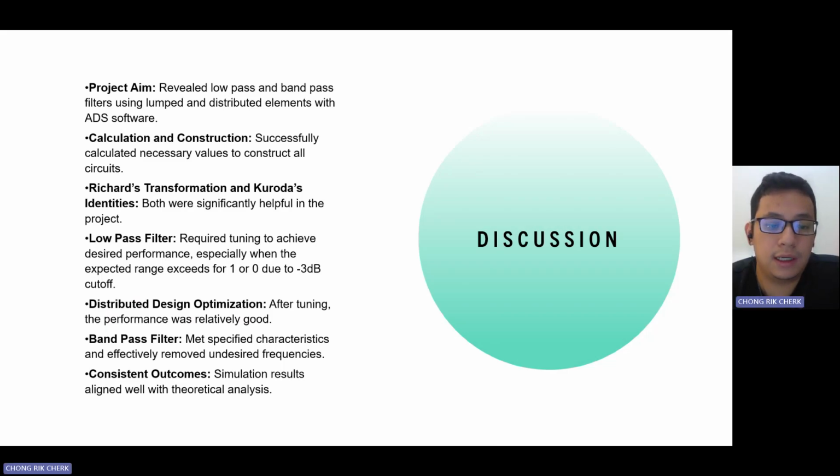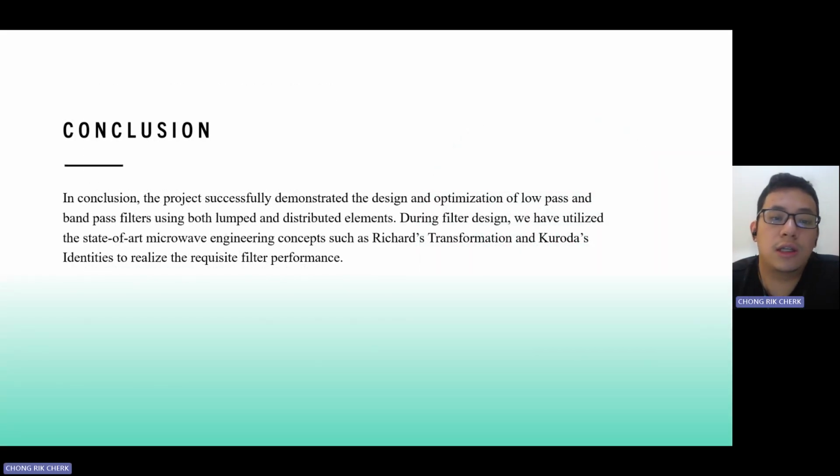As for the bandpass filter, it meets the characteristics and effectively removes undesired frequency. So yes, the simulation results are aligned with the theoretical analysis. So in conclusion, the project successfully demonstrated the design and optimization of a low pass and band pass filter using both lumped and distributed elements. And during the filter design, we have utilized state-of-the-art microwave engineering concepts such as Richards transformation and Kuroda identities to realize the requisite filter performance.